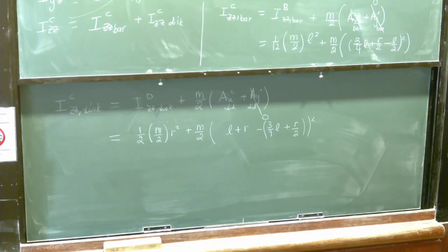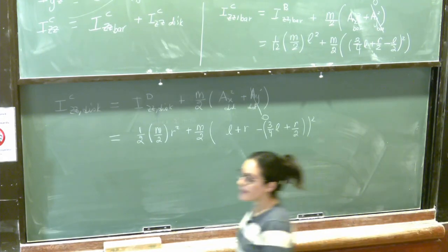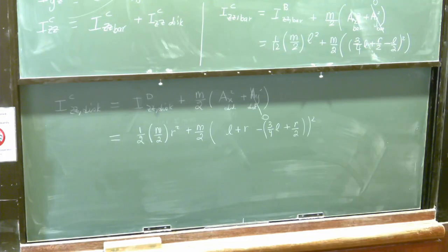So you can do all the calculations, and you'll get a differential equation of motion here. ICZZ, if I go back here, at the instant considered initially, small EX is equal to big EX, so I can get the equation of motion by dotting this with EZ, where ICZZ is what we just calculated. It's the sum of these two terms.